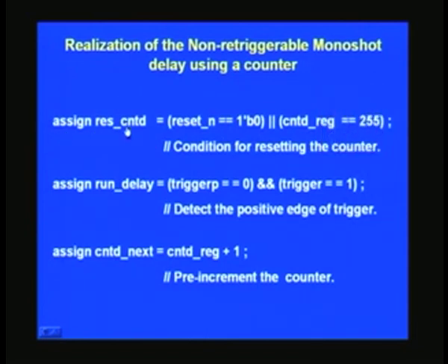So once again we have an assign statement for resetting, that's also a register as such. So here we have combined, earlier I said we should avoid else statements not to cross 5. So here probably it crossed by 1. So I have combined two similar statements right outside here, and notice that there was an asynchronous reset inside when it is 0, and then the counter value also does the same thing of resetting the counter itself. So why not combine both in a single statement, and this is the OR statement that is doing it here. So this is a logical realization, and each of them will return a 1 if the condition is satisfied. For example, if counter 2 is 255, then it returns a 1 and this will influence this reset signal as such.